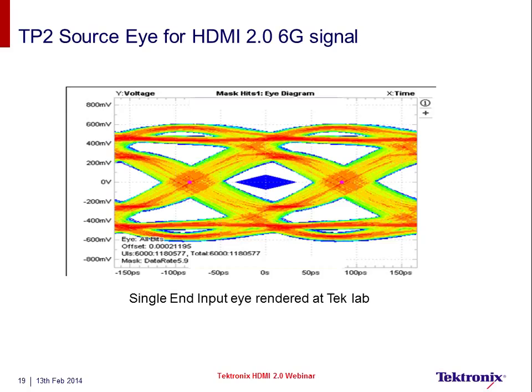However, to overcome this particular aspect of technicality, what we have added is the differential voltage test at TP1 to ensure that the signal level does not exceed plus or minus 780 millivolts. So, with the removal of the top and bottom mask, if any design team was looking at ways and means of adapting pre-emphasis levels, that's also under control now with the test of differential voltage added, and the TP1 signals should not exceed plus or minus 780 millivolts.